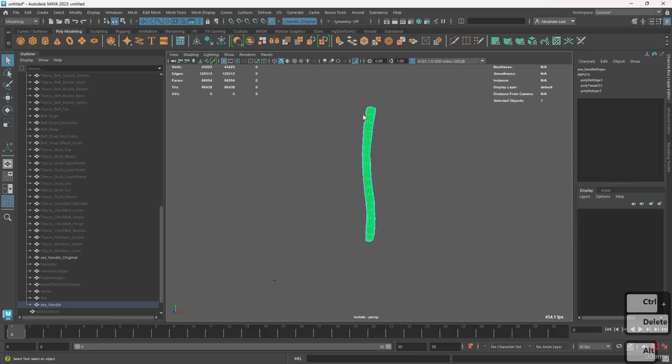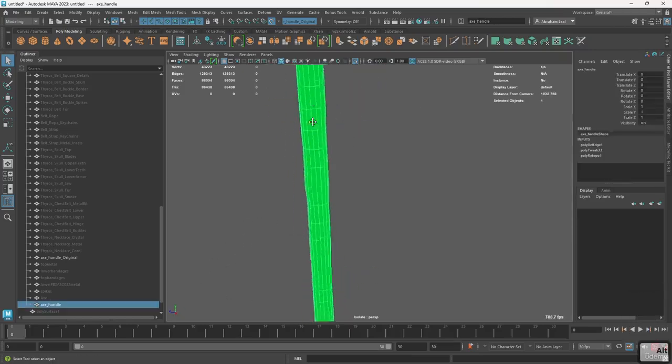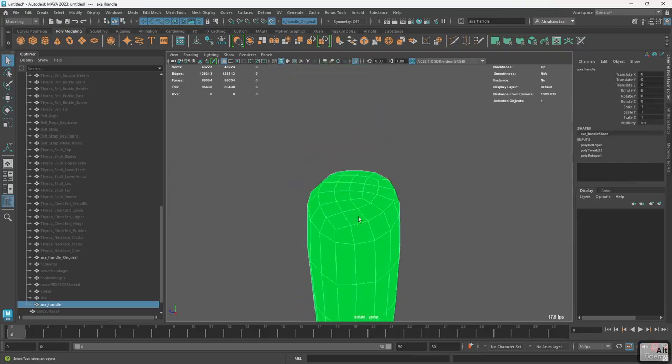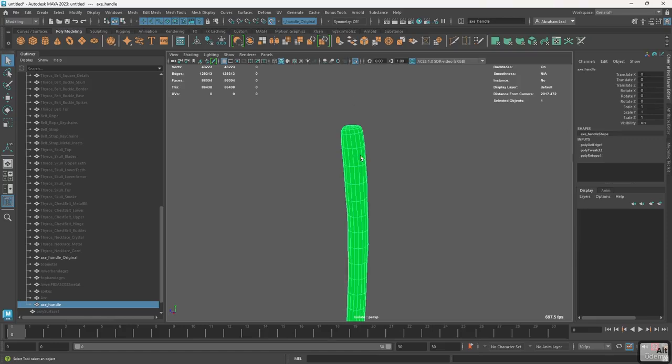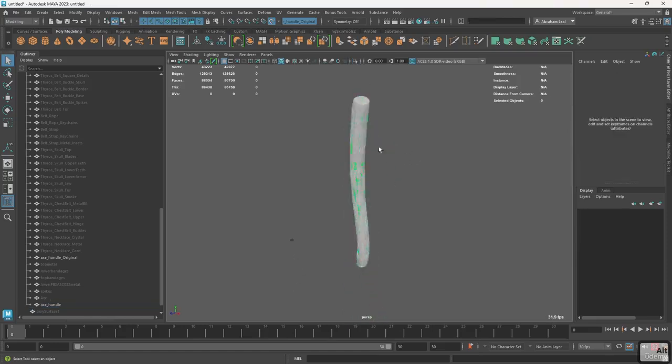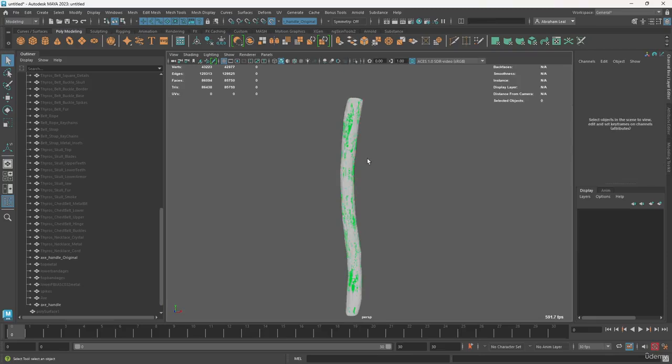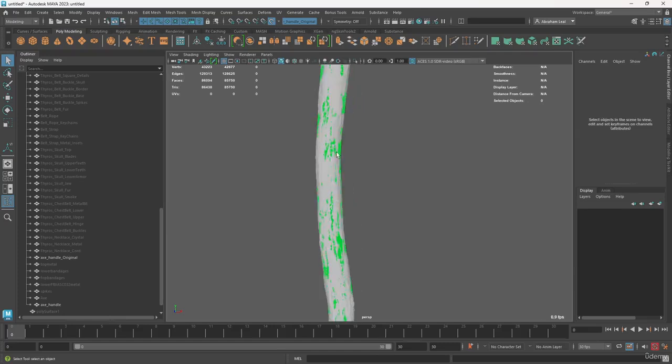So we just delete that, and we just went from 800 faces to 688. So this is perfectly fine. And I could even reduce some of these lines right here. I don't want to do it right now because it's going to create a little bit of a mess. But you can see how the automatic retopology process could potentially be really useful for things like this.